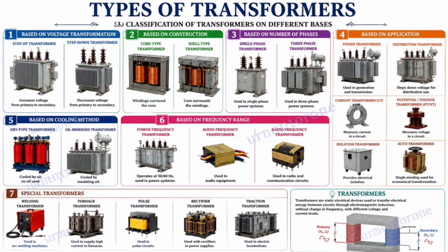Based on the operating frequency range, transformers can be classified into three: power frequency transformer, audio frequency transformer, and radio frequency transformer. The frequency of a transformer dictates its core material, size, winding design, and typical applications, as higher frequencies require specialized materials to minimize core losses.